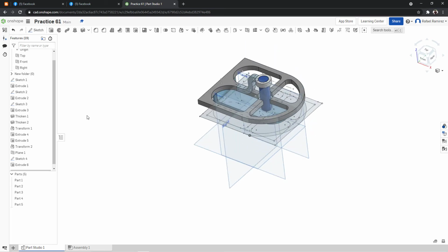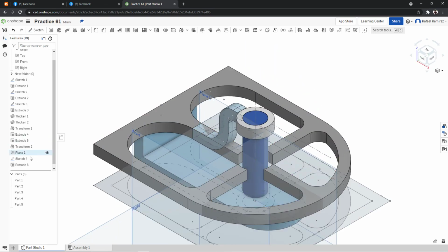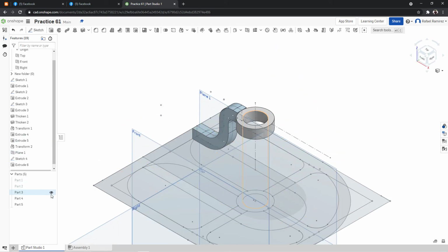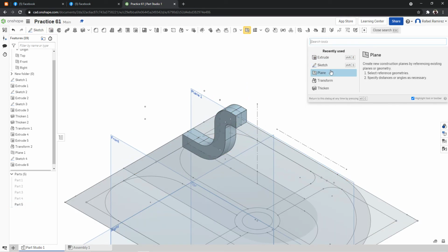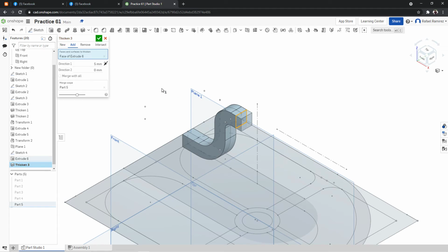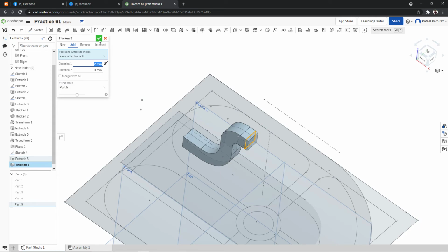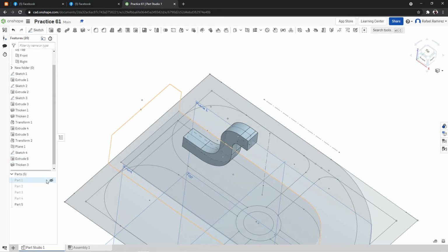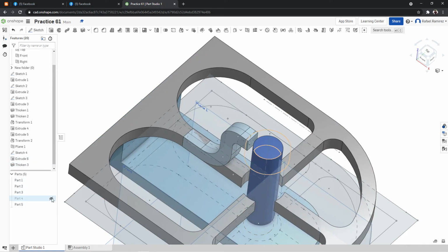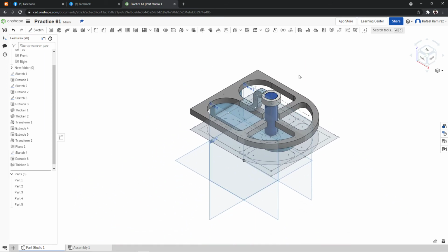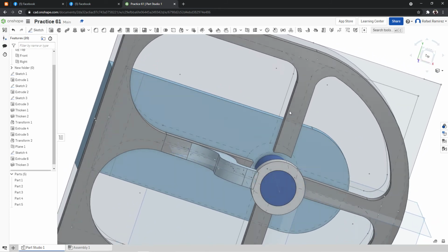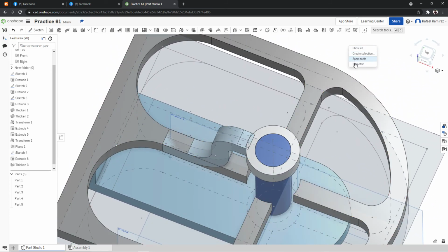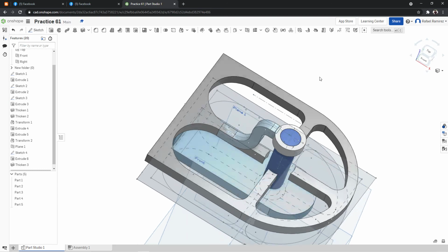So in order to do so, let me hide the other parts. I'm just gonna thicken this portion here by 2 millimeters in order to cover the gap, in order for me to use the merging tool. Okay, it's already overlapping and there is no such gap, so we can use our merge tool.